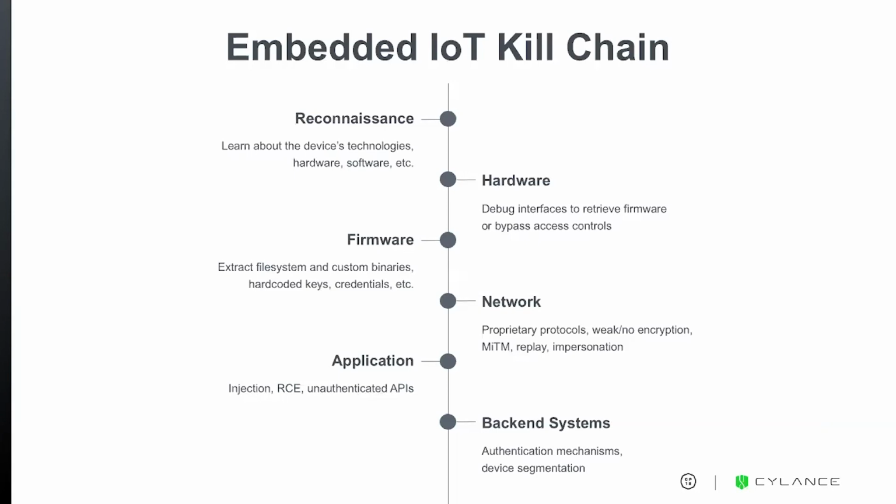Now, if the manufacturer in question has not made a request for privacy, you can find some very good results there, such as operating diagrams, or operating descriptions of what the device does, engineering documents and block diagrams of circuitry. At a minimum, you'll find what modulation it's utilizing and what frequencies it communicates on, which you can extrapolate a fair bit of information from. So that's just a couple examples, right? But the idea there is, do some good Googling, look in some sources that you've known to bear fruit before, and see what you can find out about the device, right?